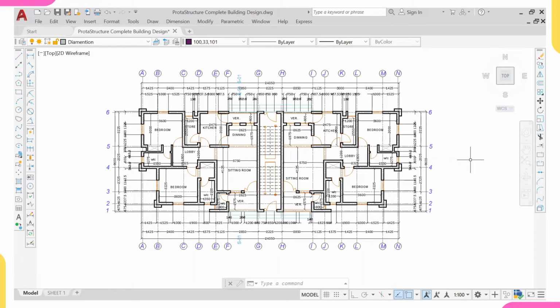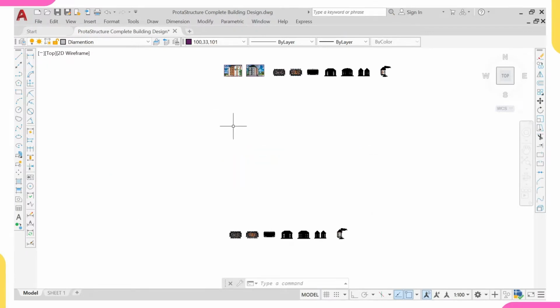These are the things you study in your architectural plan, and also study whether your architectural plan has a basement, because if it has a basement, our structural framing must be done on the ground floor plan, not on the basement plan. And if it has a basement, you should know that you'll be having concrete walls to retain the soil. Also check whether there is an offset or any cantilever.